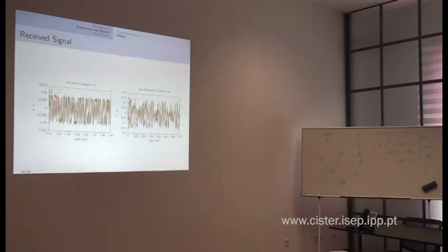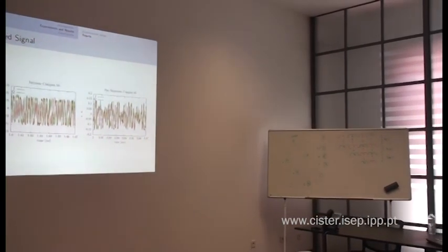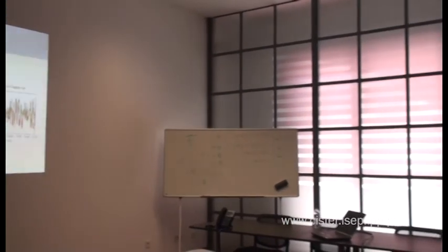In order to solve that, I mean, this is a core problem in communication systems when you have this constructive baseband interference. It's used, for example, in digital television broadcast. Those transmitters that are used to broadcast digital television, of course they have much more resources than you can have in a sensor. So they can afford to do GPS type synchronization of the phase, and they do funny stuff. But at the end, at the length of the wavelengths, you will have areas where they constructively add up and areas where they destructively add up. And the only way you go about that is physical layer signal processing. So you end up coding the signal so they never have the same amplitude and you can still decode.